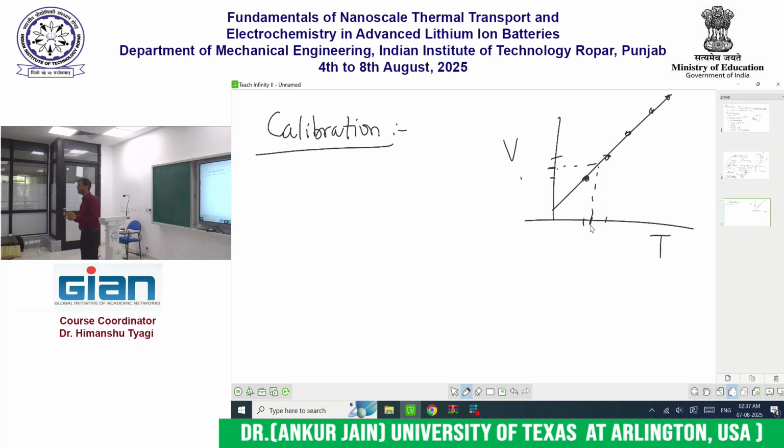The quality or the uncertainty of my actual measurement depends critically on the quality of my calibration. I cannot measure any more accurately than the accuracy of my calibration. If I calibrate it only at a few points, I calibrate it at 25, then at 30, then at 35, and then at 40, then I cannot report the temperature measured to be 26.3 degrees Celsius. My calibration was never as accurate to be able to tease out the first decimal here.